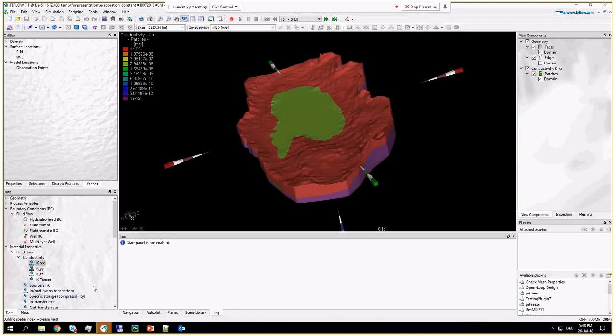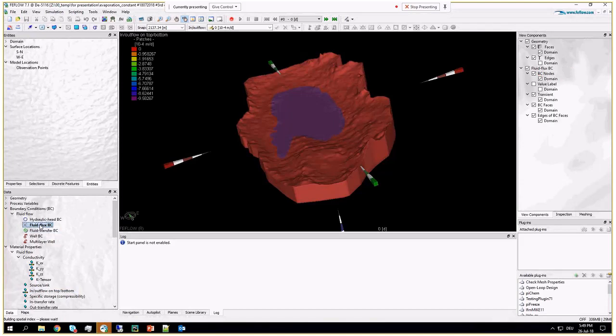Typically, if you want to set evaporation in FEFLOW for this system, you have two alternatives. So actually three alternatives. So you have the so-called In/Out from top/bottom. Many of you might know this boundary. It's basically a fixed prescribed flux, meters per day or millimeters per year. You can have a fluid flux BC, which basically has the same units, or I know some guys doing a so-called fluid transfer BC. So you can just simulate a certain head, which can be the head of the groundwater on the salar, no? And with this head and a linear relationship, control the outflow from the groundwater to the atmosphere.